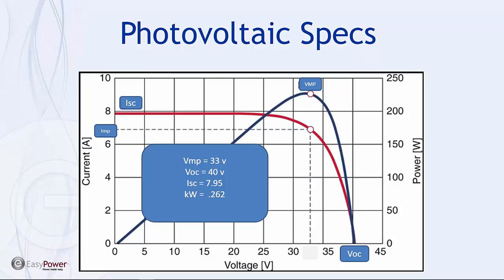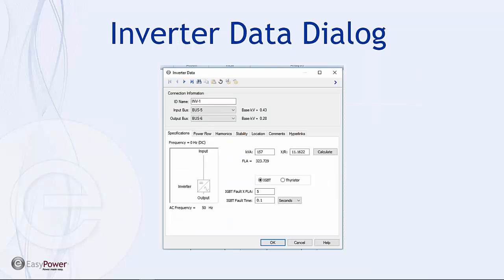Likewise, there's a need to deal with the inverter setup, and that becomes one of essentially converting or verifying the power output capability of the inverter and then matching it with the model. Currently, we just use the IGBT model because the thyristor hasn't been completed yet, and this is an inverter model that we use in other elements as well. So let's try this out.